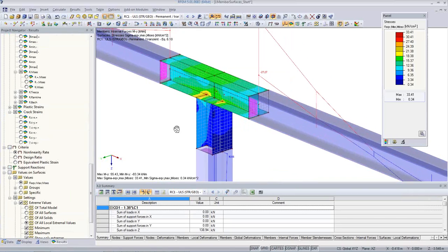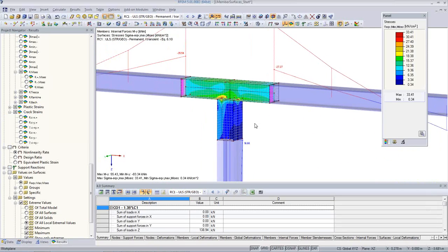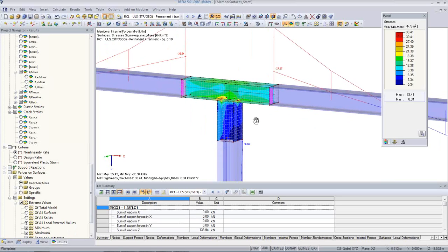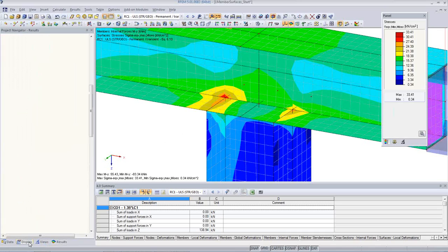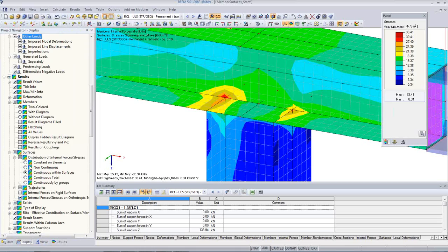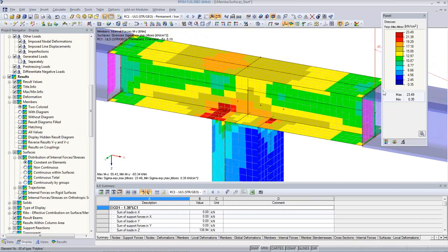We see here now the results, and I'm interested especially in the surface results. We see here now we have the equivalent stress 33, so it's drastically smaller. But as I said before, because we are reducing the stiffness only as a constant per finite element, we should look at the results only in the distribution constant by element. So if I see this, then I have 23.49 as the maximum sigma equivalent von Mises.